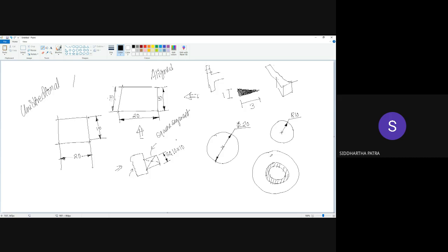So you basically have these circular holes. For the sake of simplicity, I'm just assuming there are four of those, and then you draw the center line on which the center of each of those holes lie, and then you put a dimension about so-called PCD or pitch circle diameter. So this represents the diameter of the center line, which contains the center of each of the circular holes.